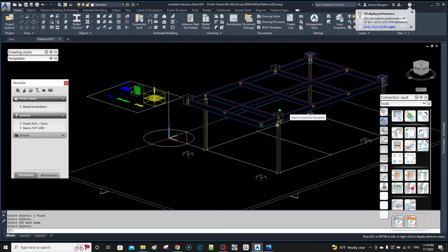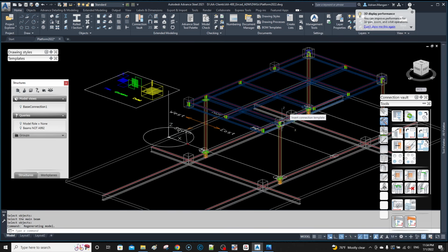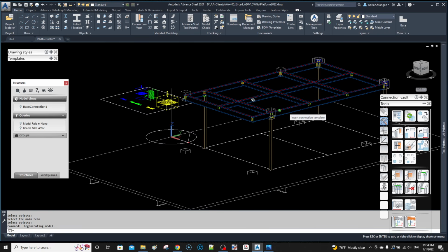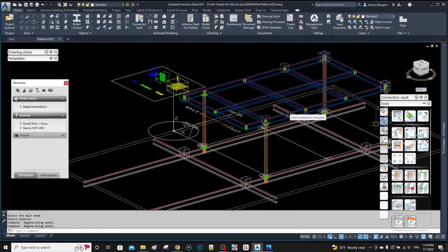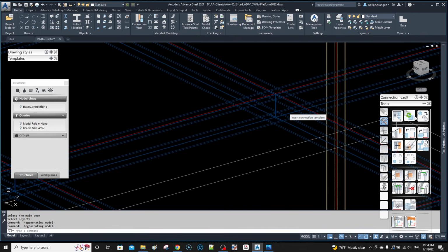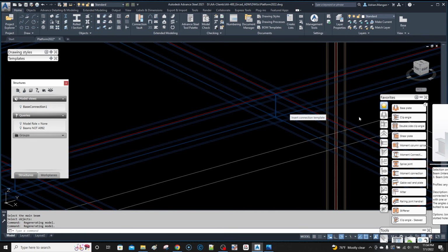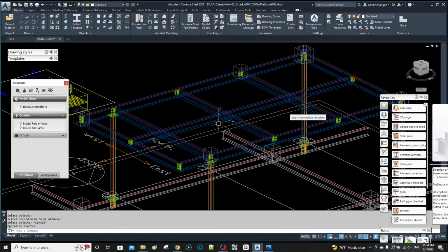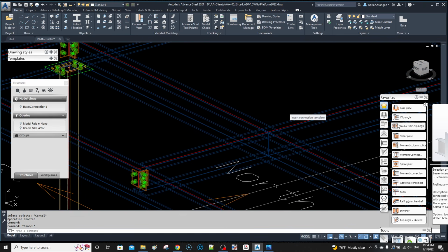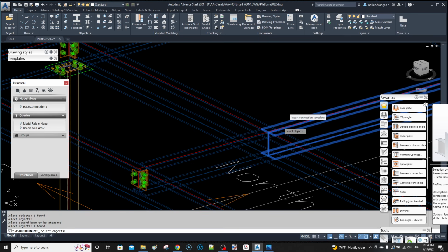So we just need to do the connections in the middle, right? So what I'm going to do is I've got to do the double connection. So it's probably good practice to do one of these and then go straight to your double connection if it's the same size beams. So I'll go straight over here and select this one and then go left. Oh, sorry, I forgot I switched, right? This one is the one that we split. So this is where the double connections are going to be. So let's start on this end and this is going to be the main beam, and then go left and then go right.